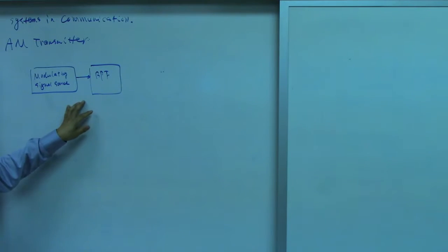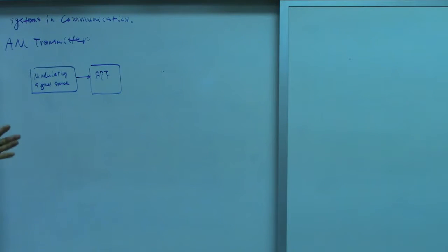A bandpass filter is always a good practice. No matter where you are, you can just put a bandpass filter, right? So only let the frequencies that we are interested in pass. Because in any communication system, or even any systems, you always have some thermal noise or other noises. You don't want that, right? It makes your system unstable. So you just put some bandpass filters anywhere you want. It's not a bad idea.